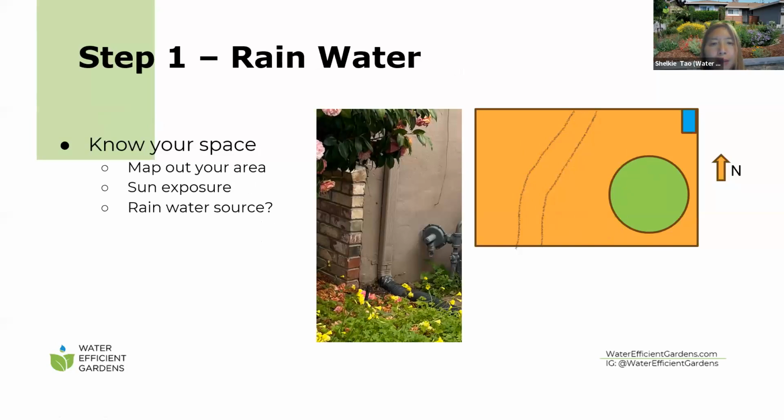The next thing to find out is where your downspout is, because that's how we find out whether we can design a rain garden and where to put it. So just go to the corner of the house and see where that is located. For example, if the downspout is right here at this corner, then you can put something there to indicate that's the downspout.